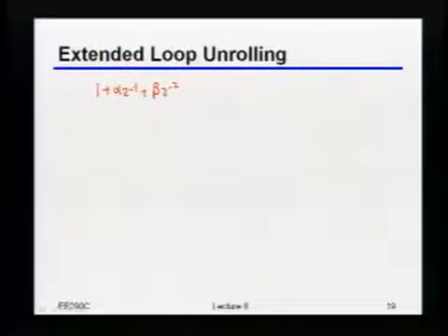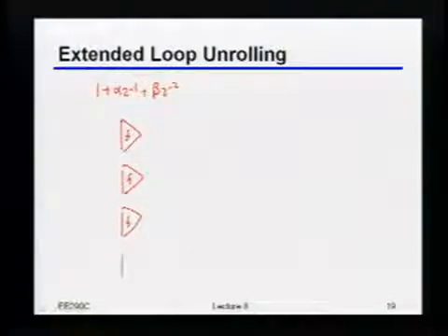I'm a circuits guy, so how many comparators do I need? 4. Yeah, I need 4 comparators, right? Because now I have basically 4 possible data levels that I'm going to be dealing with. Because now I've got 2 previous bits that could have ISI on me, right? So I have to deal with all of the combinations of those 4 possibilities. Okay? So what would the thresholds of each one of these be shifted by? So let's say this is my V in over here. What would I shift the threshold of each one of those by? And let's just walk through the list.